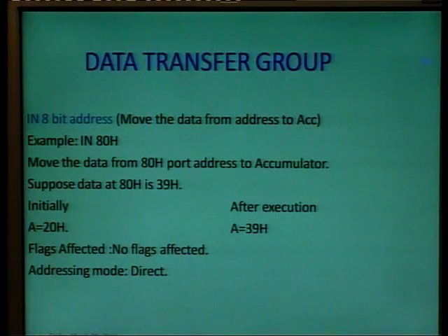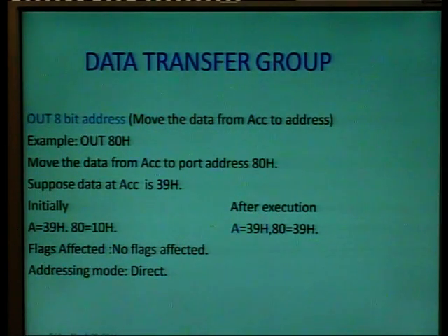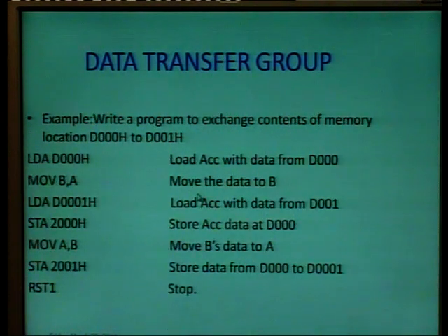Then IN moves the data from the address to accumulator, and OUT moves data from accumulator to the given address. Here this 8-bit address is the address of the port. This is some example program.